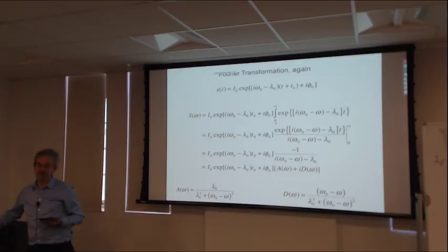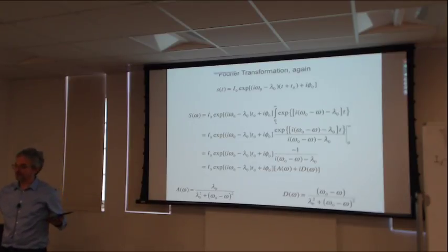But that bandwidth is probably way larger than your spectral width. And that means all the noise outside your spectral width is going to alias and fold back into your spectrum. That seems like a really bad idea, doesn't it? The signal to noise is going to be degraded by all this noise outside the spectral width folding in.